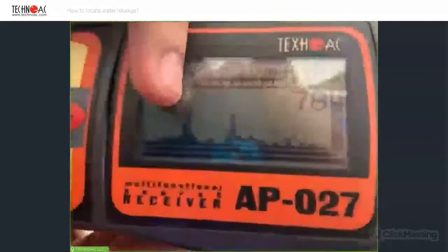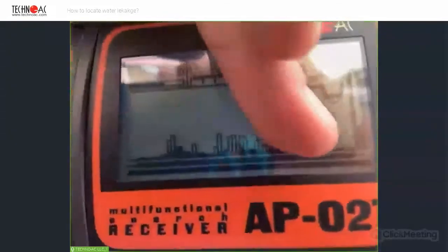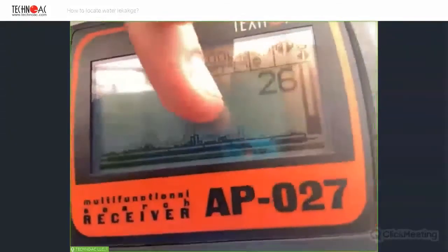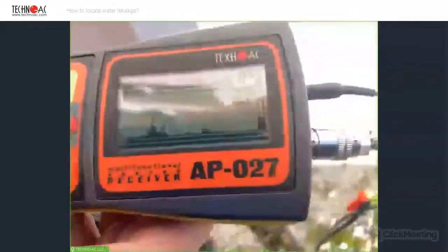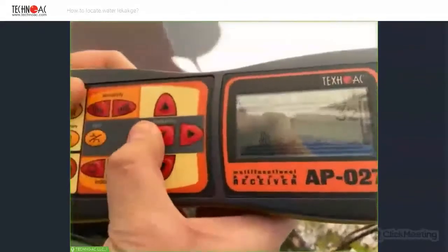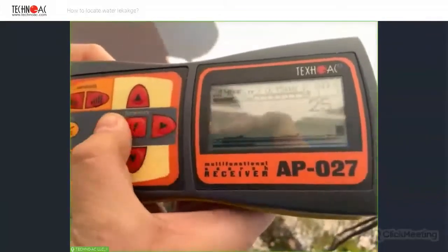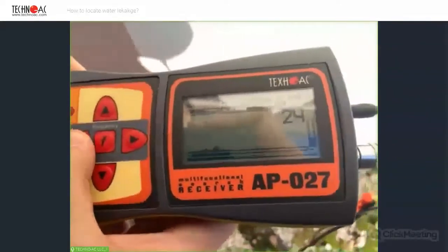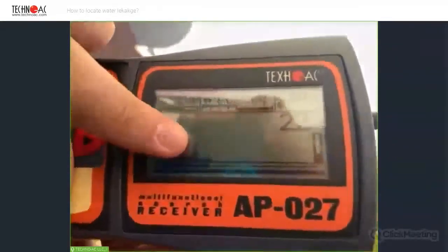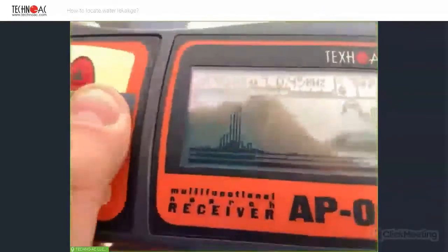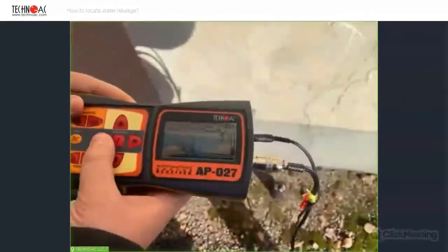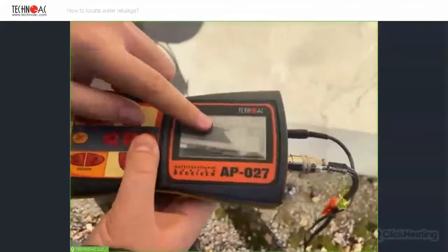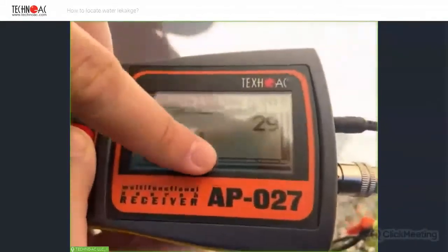We know that our water noise is lying in this particular spectrum. We have to cut off this spectrum from the rest of the frequency range. So I will be pressing the left and right arrow keys, and I will be removing the rest of the noise from the spectrum. You see, when I'm changing the settings by pressing the left and right arrow keys, the scale here is also changing, and the scale here is also changing.